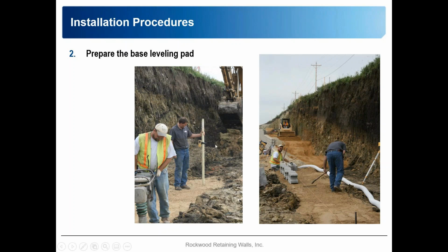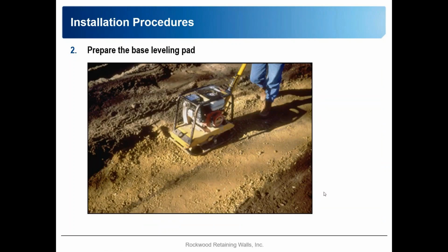Here you can see that as they're adding gravel and filling up that trench, they're trying to get relatively close before they start fine-tuning it by getting the elevation fairly close. And then here they're adding the fine-tuning with rake and other tools. Here's an example of a vibratory plate. You can see the first pass that I made here, how it just densifies it. Is that 95% standard compaction? I don't know, but it's good quality material and it's been compacted with the proper piece of compaction equipment. A couple, 2-3 passes over that type of material with a vibratory plate should be sufficient.